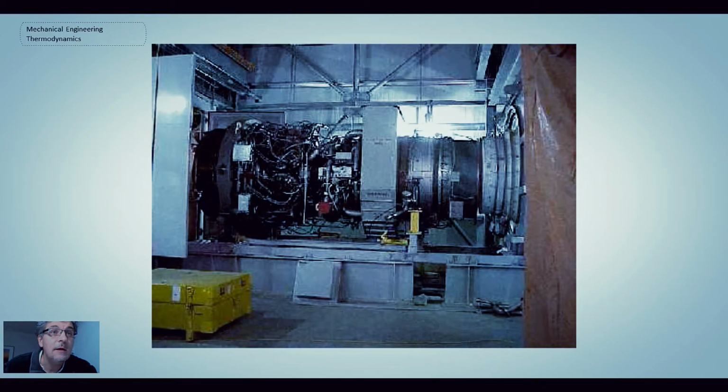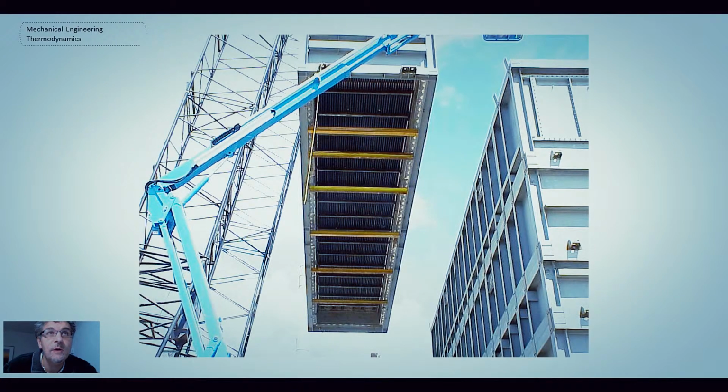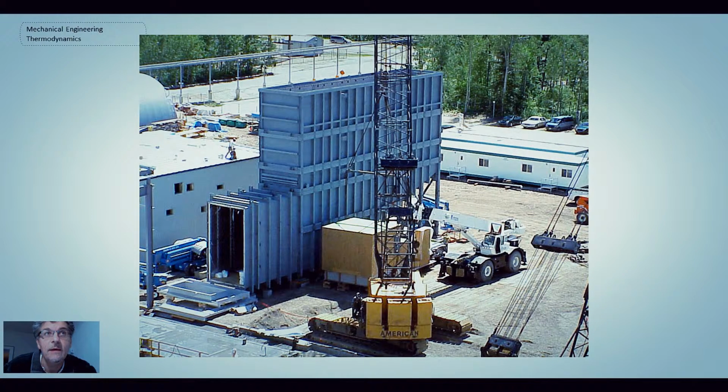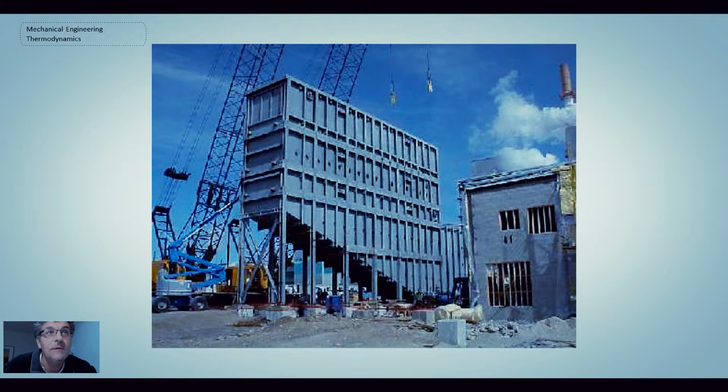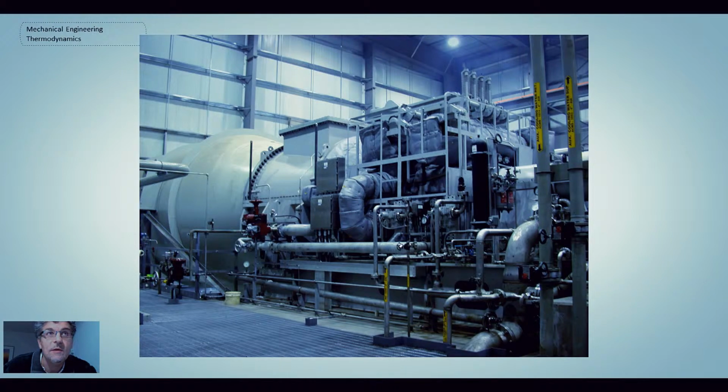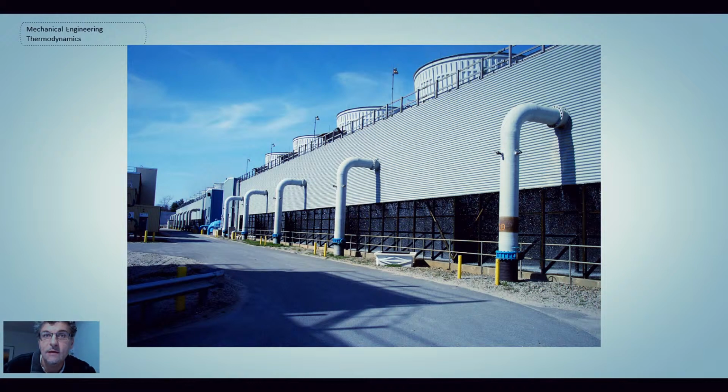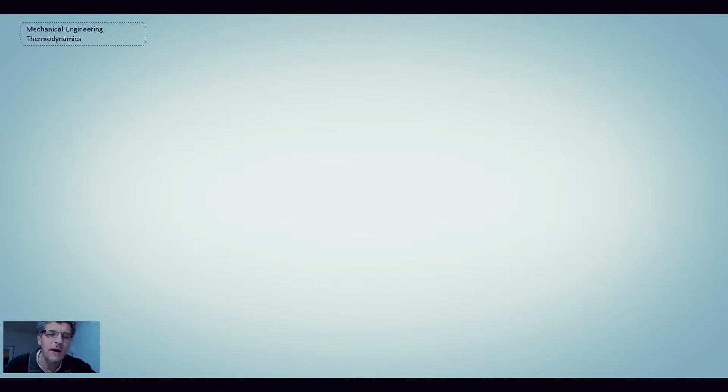systems. And what we can see here is an aeroderivative gas turbine engine that is converted for use for industrial applications. The exhaust gas would go out through a heat recovery steam generator, as you can see there, and then it basically turns the flow upwards through the heat exchanger. That's the construction of one of these systems. The heat would then be recovered, generated into steam, sent through a steam turbine like we looked at before, and eventually going into cooling towers and rejecting the heat to the atmosphere.